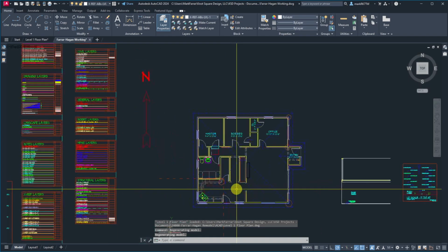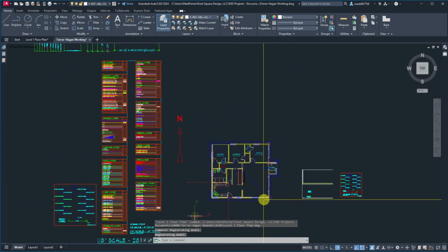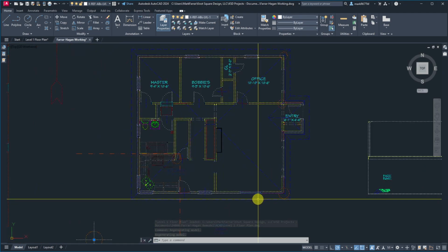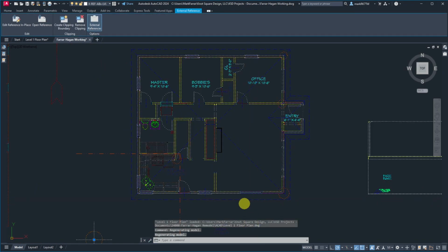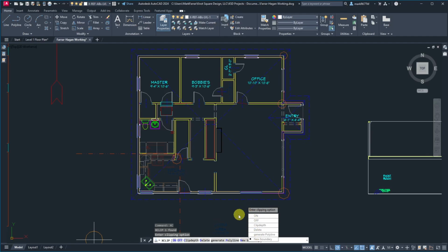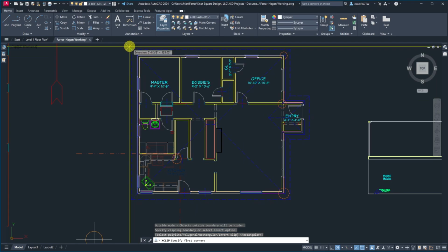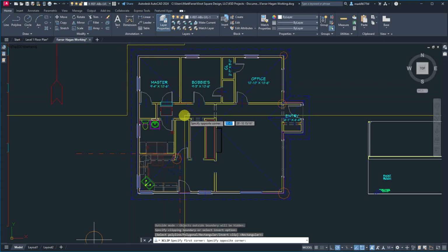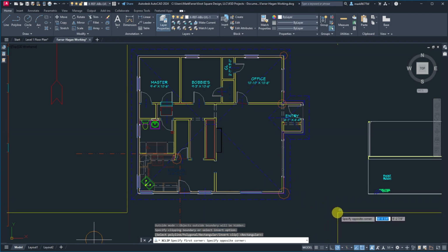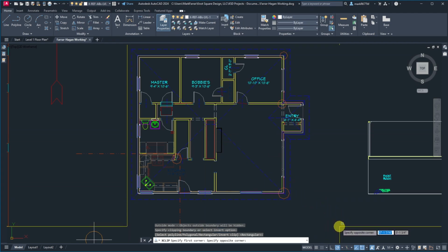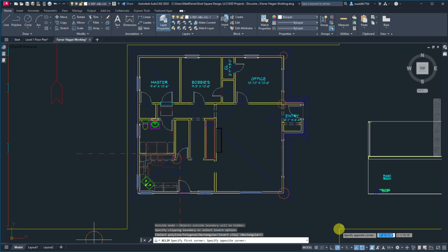So that's there, and you can see this drawing's there too. Well, this you can do what's called an X-clip. So XC, enter, and then I want it to be a new boundary, so enter, rectangular, and then I want to just draw it. There's going to be porches and stuff added to this eventually. So for the moment, I can probably go safely from here. I'll catch that front porch and my side porch by going maybe out there.